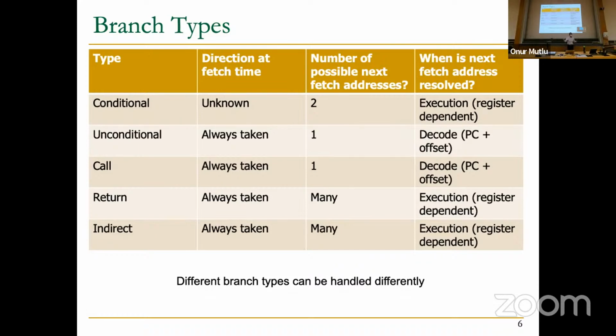So basically, gotos enable you to jump to any point in the program, but it's a very irregular structure, right? Calls and returns are very methodical, which enables you to match the nesting level. And existing hardware behaves that way also, basically. You fetch a return instruction, you look at the top of the stack and say, oh, in the call return stack, this is where I should jump. So you pop the program counter over there, and that's your next fetch PC in that case.